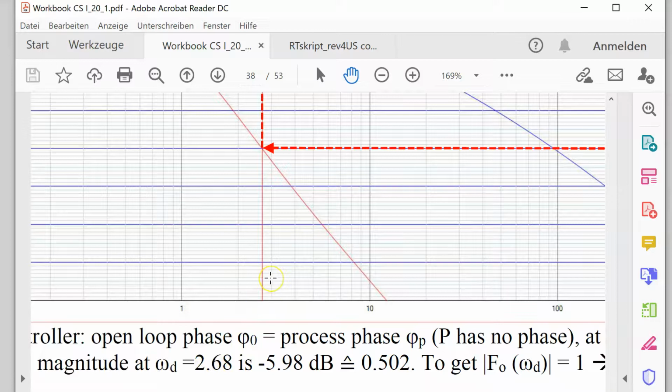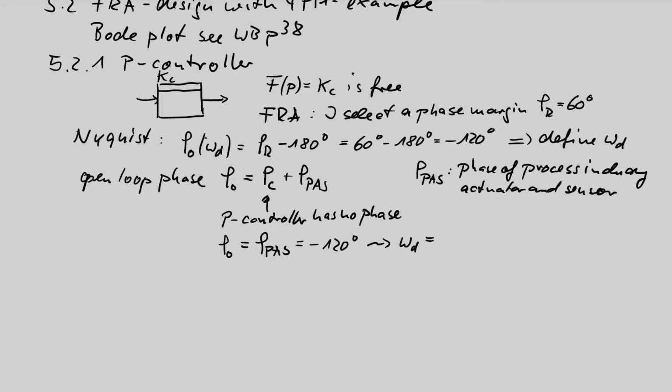So the definition of my phase margin leads to exactly the result for my speed indicator, 2.7. Okay, with the speed indicator I can estimate my Tmax value of a reference step response as roundabout 4 divided by 2.7, which, rounded to a maximum of 2 significant digits, I can say is 1.5 seconds.